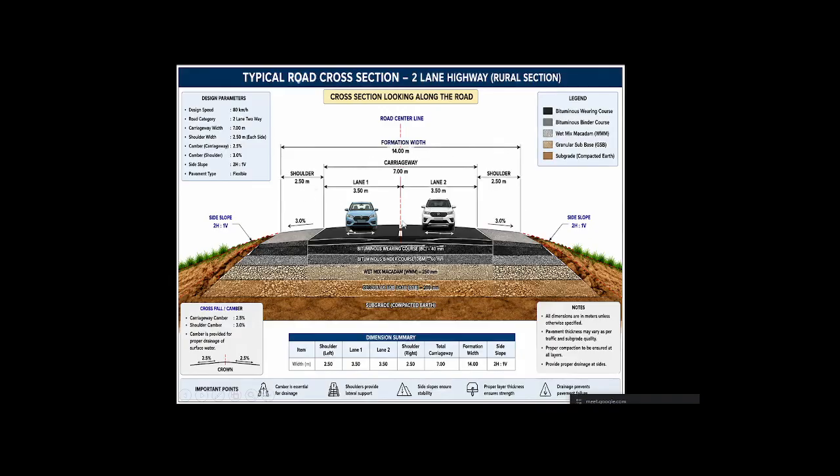Now, an assembly represents the typical cross section of the road as you can see in the figure. Think of it as a template that defines how the road should look at every chainage. So now in front of you there is one template, and you can see that at every chainage the road looks like this.